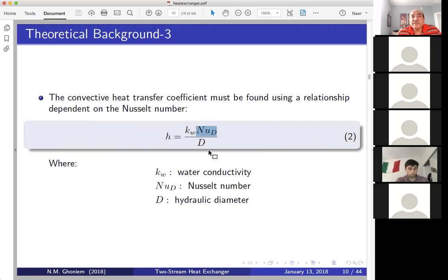And usually the convection is much more, so the Nusselt number is going to be probably like 20, 30, 40, 50. The higher it is, the better we're going to remove that heat. If we know the Nusselt number, which we should, then we will be able to calculate H. So now you see the story is getting more involved.